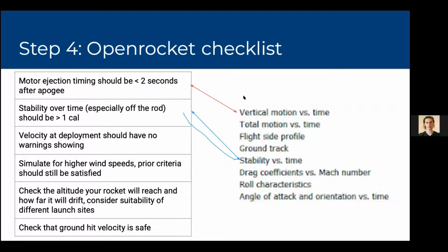Just a second. So yeah, while you boot that up, there is a value that is telling you the velocity of your rocket when the parachute is deploying. This is something you do need to keep an eye on, because if your rocket is moving too fast when the parachute deploys, it'll be like sticking your hand out the window, holding a parachute while you're going, for example, 70 kilometers an hour down a freeway, right?